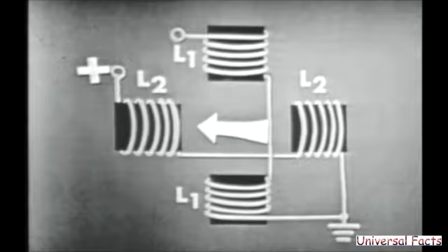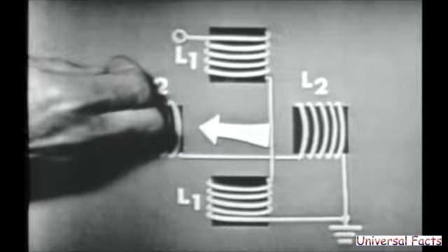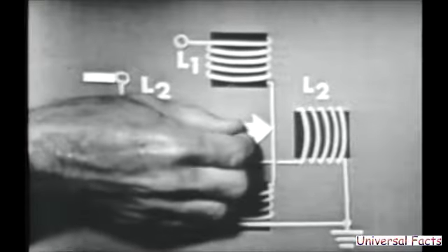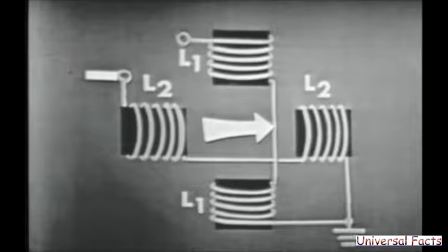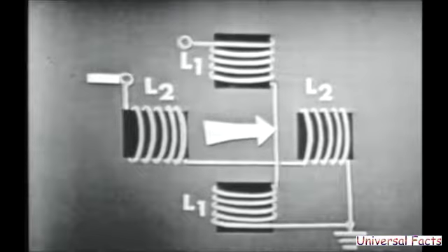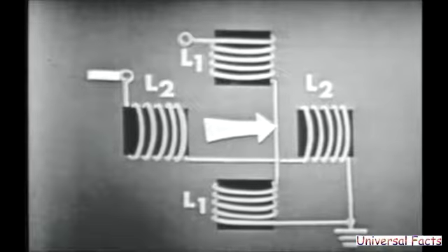There we go. And if we reverse the polarity applied to L2, go from positive to negative again, we'll, of course, reverse the direction of the magnetic field. Now, from this, you should see that we can already produce four magnetic field directions, up, down, left, and right, simply by supplying the proper polarity of voltage to each coil.